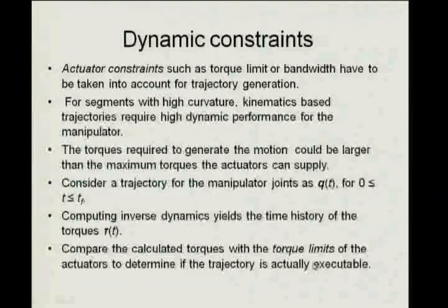So, we have to look at these issues of torque limits, that in the bandwidth in the motion is the torque limit being reached. That is one thing. The second thing is, it is not only the issue of what is the maximum torque, it is a question of how quickly the torque rises. Okay. So, what is the response speed?